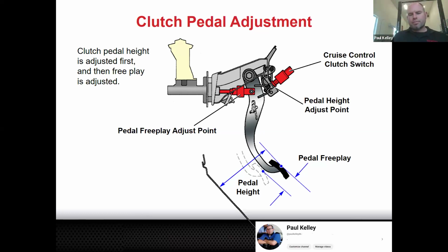It's the same symptoms. Any symptom of excessive free play, in your mind, you could think of, well, let me drive the car, but let me only push the clutch pedal down halfway. Grinding gears from a stop, it's going to be hard to get it into reverse if you can even get it in at all. But if you were to shut the car off, put it in reverse, and then start it, it would be in reverse. It would probably just be dragging. You'd be like, whoa, here we go. The clutch pedal's down, but I can't stop it. Make sense? That's all too loose adjustment. That's all too loose. In this Jeep, it's because it's got air in the system.